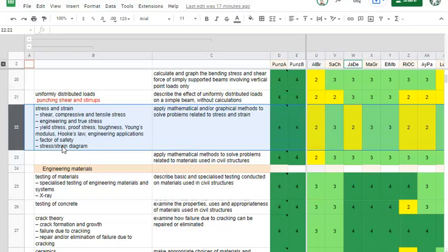Now, it's worth mentioning, when we talk about aeronautical, that the factor of safety is lower for aeronautical, not because we care less. The factor of safety is lower because of economic factors, and we compensate for that low factor of safety by doing increased testing and maintenance.